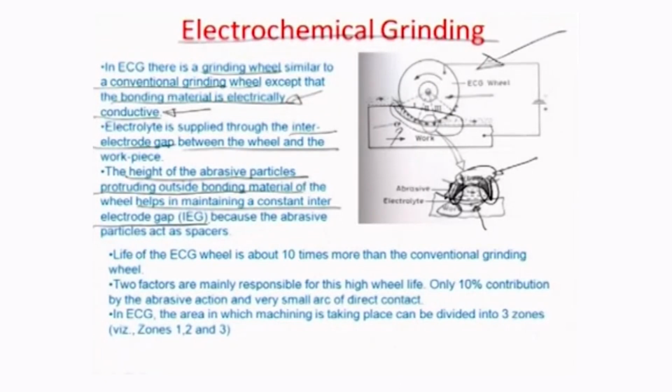In fact, in conventional grinding you have to do an operation of dressing, where after every grinding process you have to redress the tool in order to start ab initio. One of the reasons is that most mechanical abrasion results in clogging of the gap between the abrasive particles on the surface of the wheel.